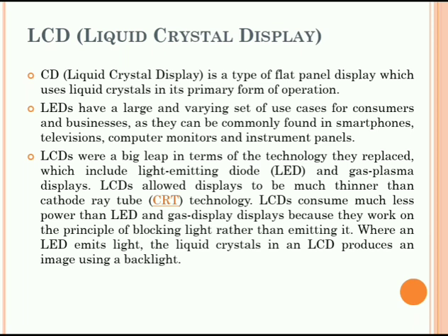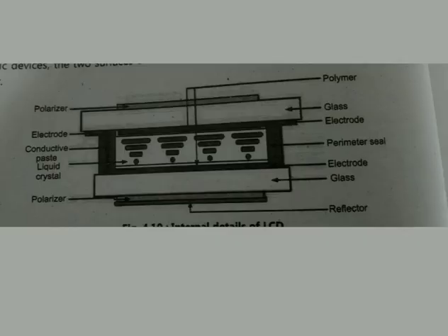The LCD glass has transparent electrical conductors plated onto each side of the glass in contact with the liquid crystal fluid, and they are used as electrodes here. These electrodes are made of indium tin oxide, that is ITO. When an appropriate drive signal is applied to the cell electrodes, an electric field is set up across the cell.